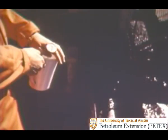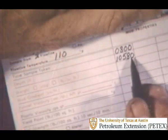And in this part, test information on the mud properties is written in. Let's go over some of the common tests. First, the mud man gets a mud sample from the mud return line and takes its temperature. Temperature affects the mud's characteristics. He writes it down on the form. In this case, it's 110 degrees Fahrenheit. Also, he records the time, 0800, or 8 o'clock in the morning, and the depth of the well, 10,580 feet.